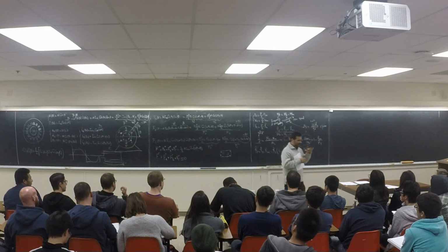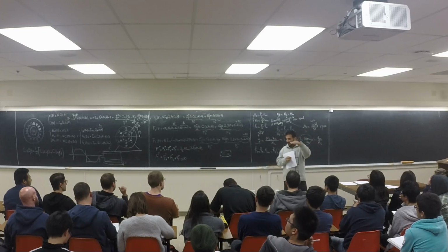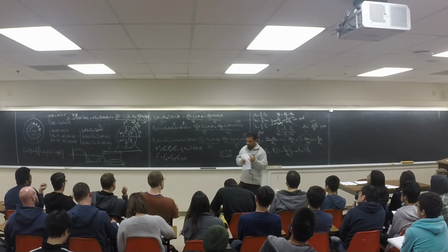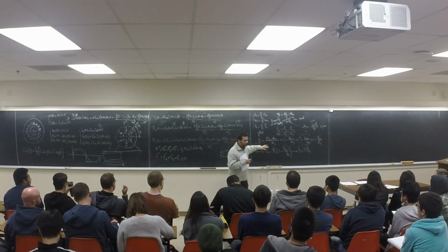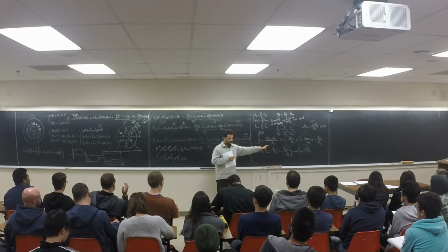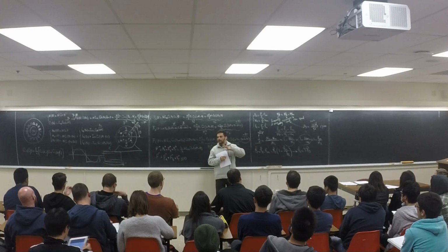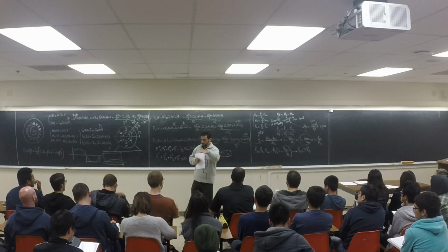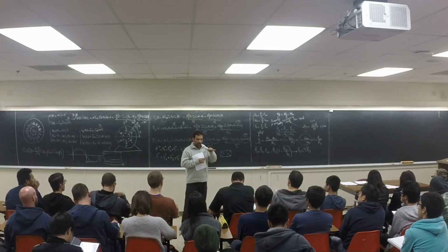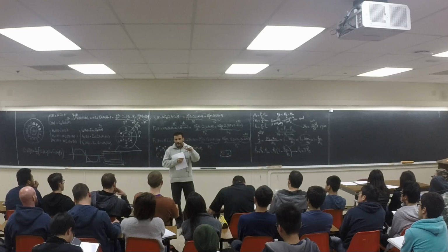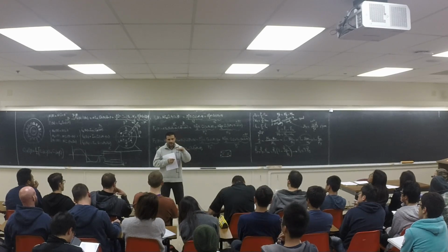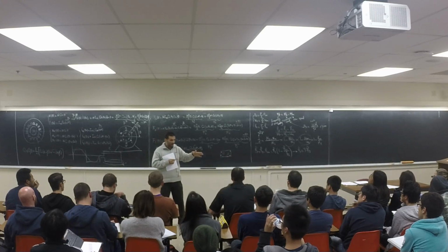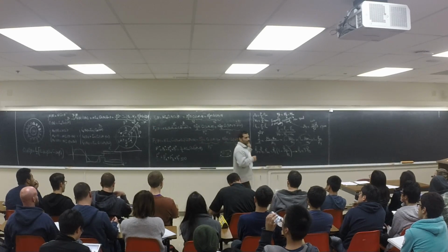Usually they design the machine to work a little bit more than its nominal value. 10% is kind of a lot; the machine is going to get really hot if you run it long. But the rated value, you can run it forever. It's going to get hot, but it's not going to be dangerous. The temperature is going to reach a steady state value, which is not dangerous for the machine. But if you run it at 10% overload, it's going to get hot and not reach a steady state number. Maybe after 10 minutes, it's going to get really hot. It's not going to burn right away, but if you run it for 2 hours, it's going to burn.